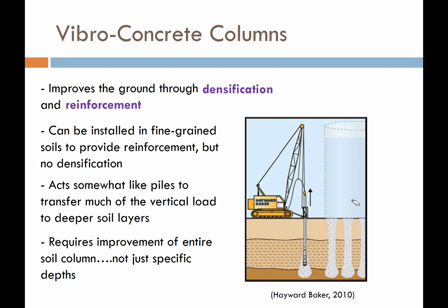One of the nice things about this is that we can install these in fine-grained soils. Oftentimes we can't use the vibro technique. We have to drill it first because the clay just doesn't compact with vibration. But the point is that we can get down and we can put this grout or concrete in the ground. But if we do it in fine-grained soils, we're not densifying anything. We're just reinforcing the soil by applying an element or a material that has an increased shear strength.